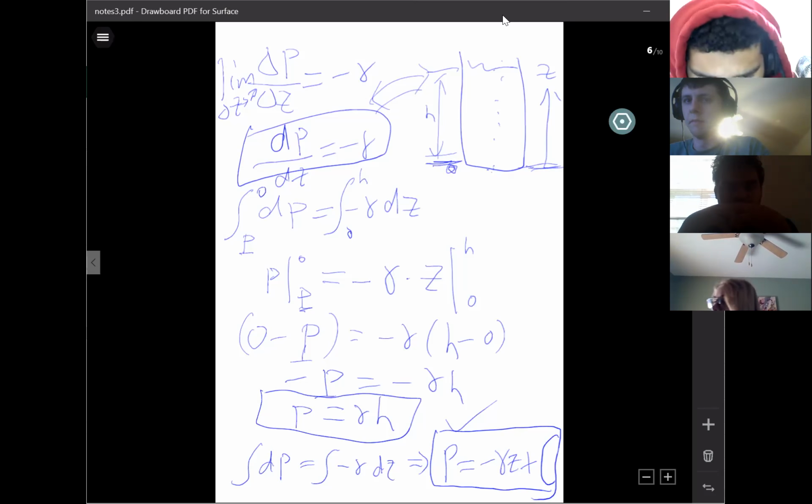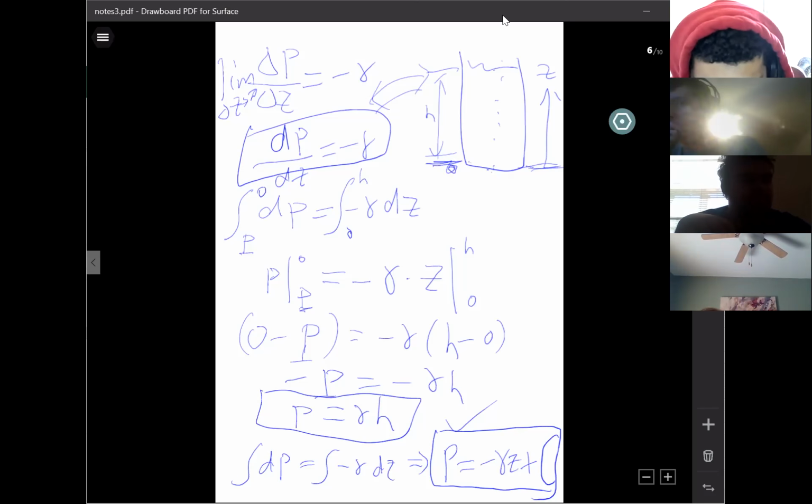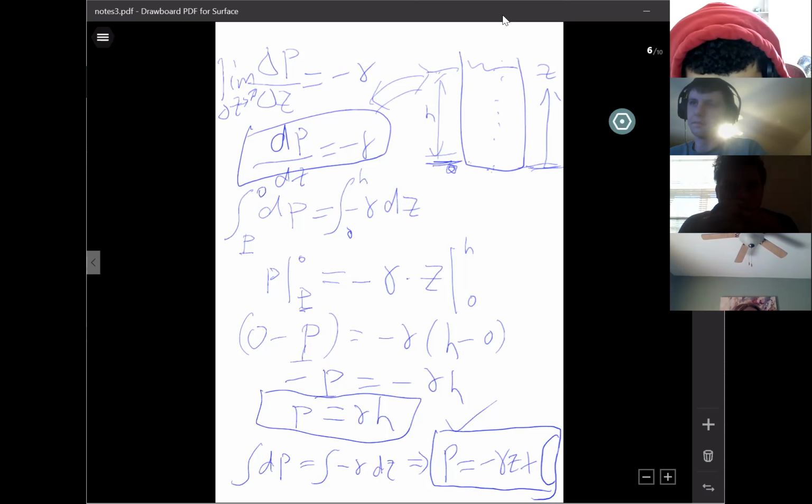When Z equals 0, you have a pressure down there. I put a letter here. When Z equals H, what is the P? Would it be atmospheric or just the pressure at the top? Atmospheric pressure, we use gauge, remember? Seems like you hesitated to say 0. Atmospheric pressure in the gauge system is 0. Please confidently say it. Yes, sir. So these are the two limits for the two variables P and Z. They have to be consistent. Did I answer your question?